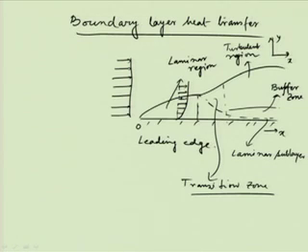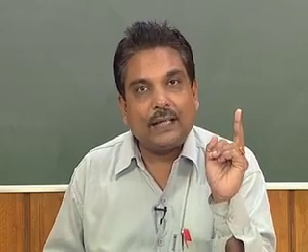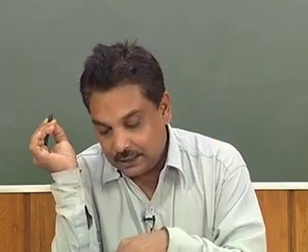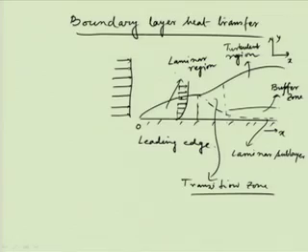At this point is the no slip condition, where the velocity of the fluid particle which is adjacent or adhered to the surface of the wall is 0. That is called the no slip condition. As we go along, the velocity gradually increases across, and then it reaches some point.